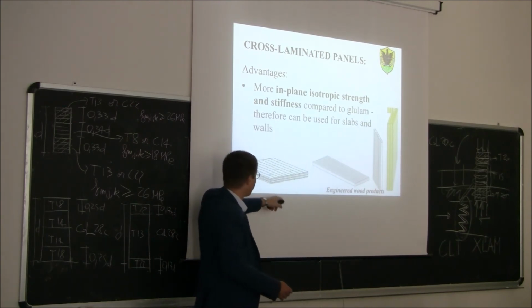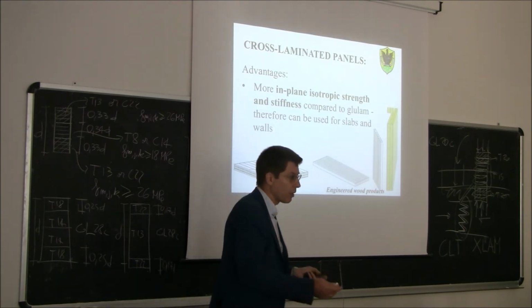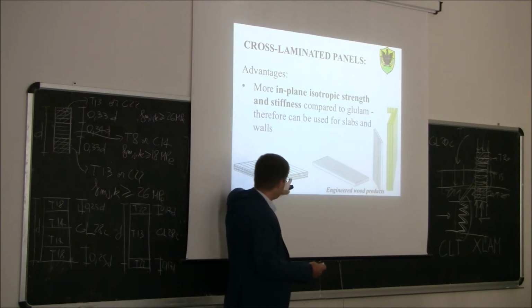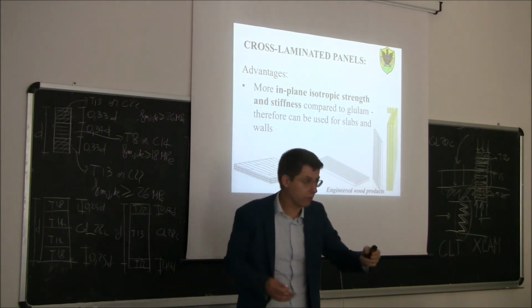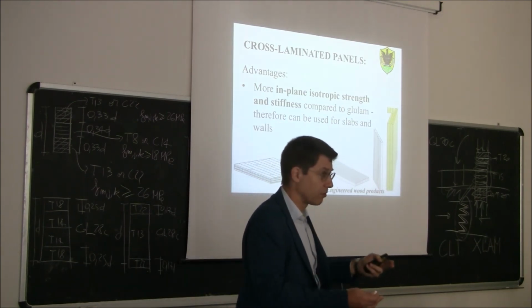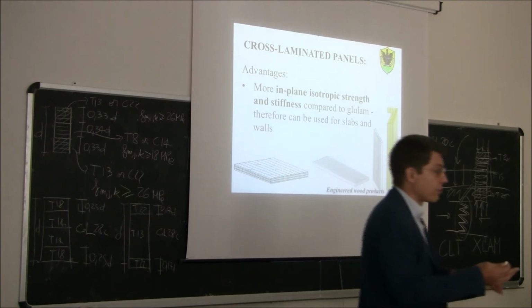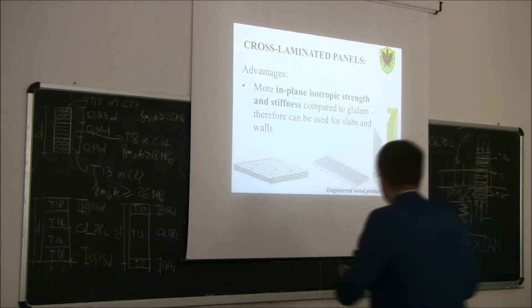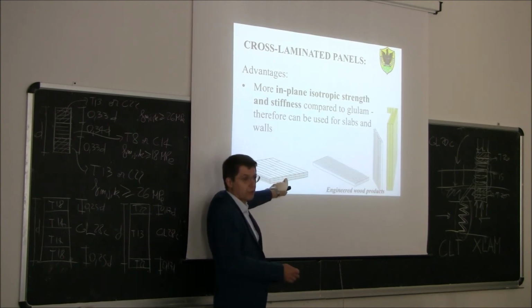So this means that, for example, if I'm interested in the bending strength, where can I expect to have the larger bending strength? Clearly here, because the layers parallel to the direction that we are talking about are fully resisting. For those layers, I can use the strength of the board parallel to the grain. For the 2 intermediate layers, which strength value should I use when I do the bending verification?